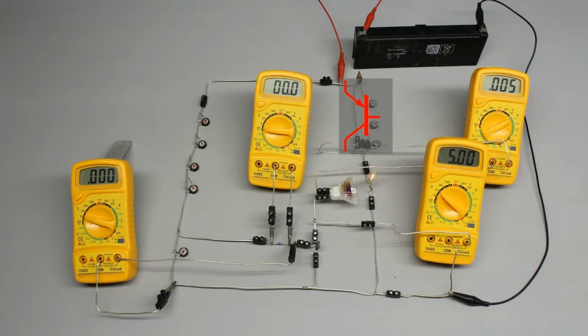Thus, we get a voltage divider consisting of two adjustable resistors, by which we can align a constant voltage drop at the NPN transistor. The resistance of the NPN transistor is adjusted by attaching a positive voltage drop at the base pin, like we did at the first measurement series. In contrast, the resistance of the PNP transistor is adjusted by attaching a negative voltage drop between emitter and base